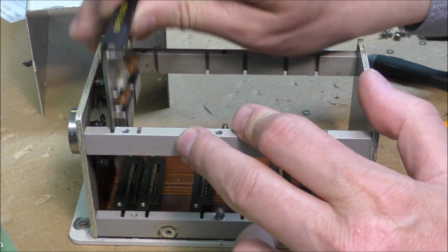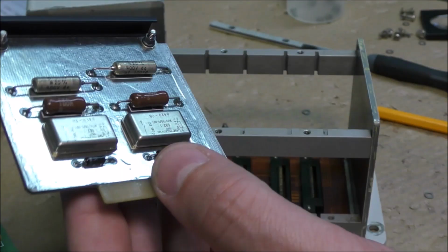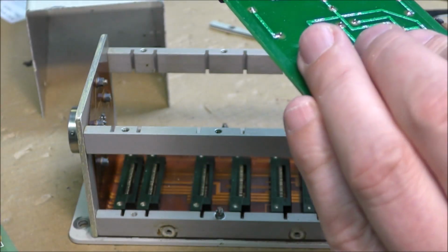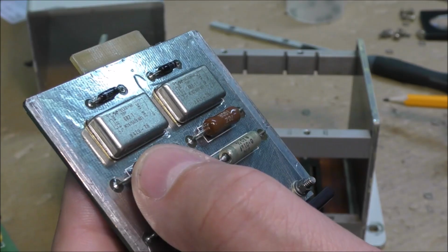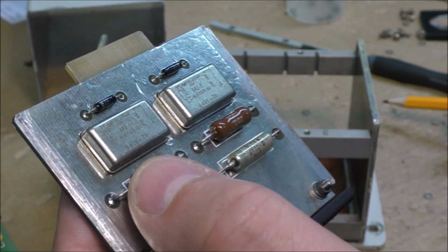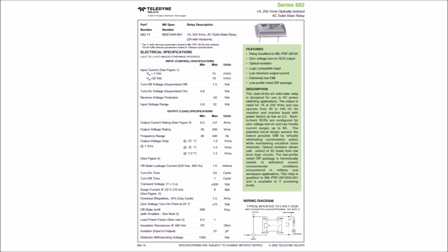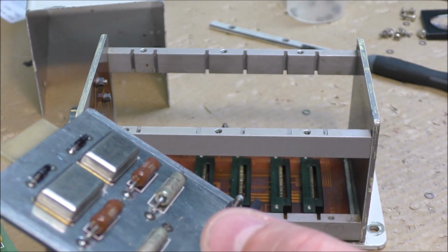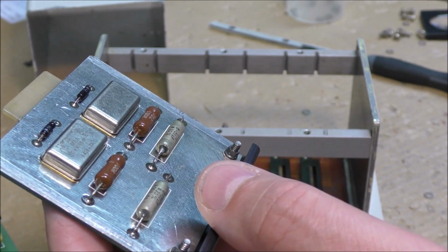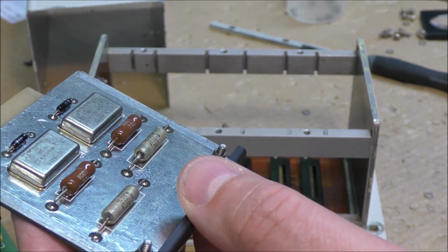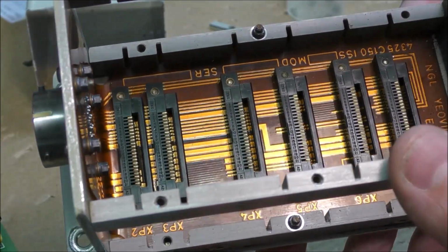The last board is the output stage. There is almost nothing on this board except two relays and an RC network. These are snubbers. You can see the relay from Teledyne, date code 84. The reference is 682-1. These relays probably permit driving valves for warm and cold air, in order to stabilize the cabin temperature. The rest are card edge connectors and also a flat flex.